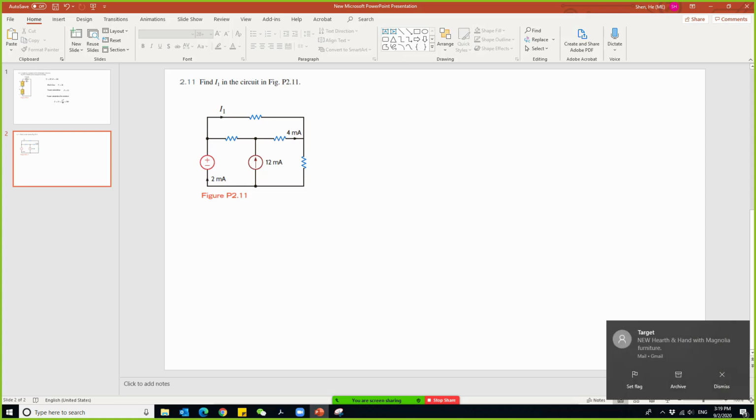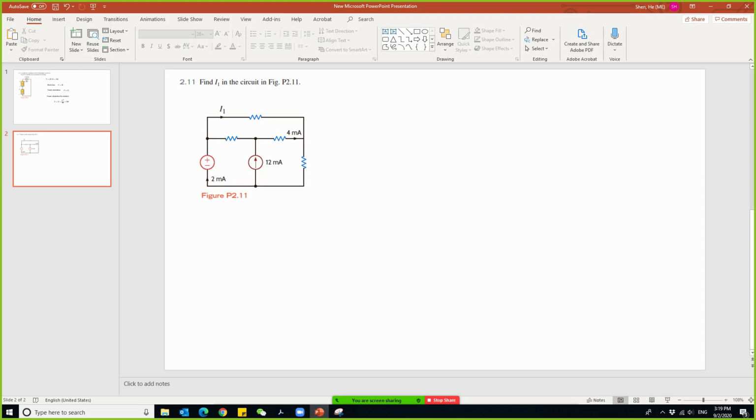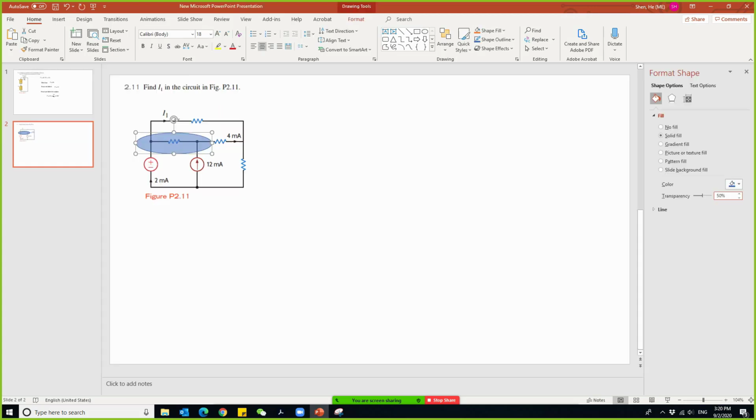Professor, question? Yes. Could you call those 2 nodes with the resistor a supernode, so that you could just turn it into the 4 currents that are either leaving or entering that supernode? Yes, that's the second method that I want to mention. You can define part of a circuit as a supernode. You can assume any part of a circuit to be one node. If I define a node over here, say I'm going to define my node A to be that. So define part of the circuit as a node A.